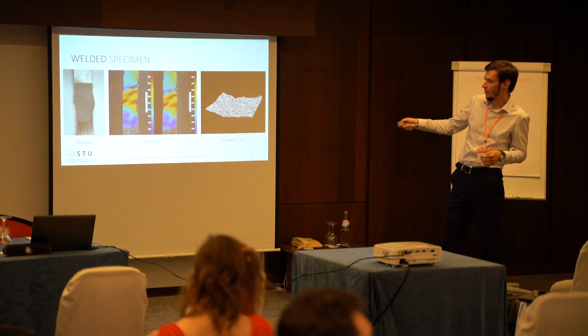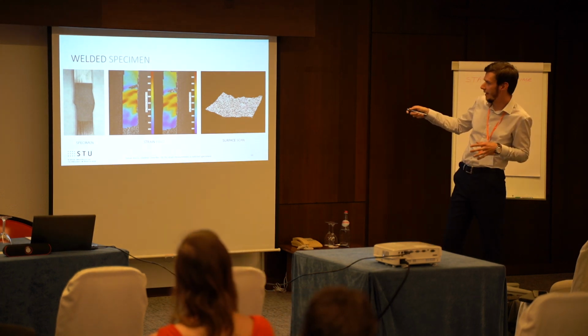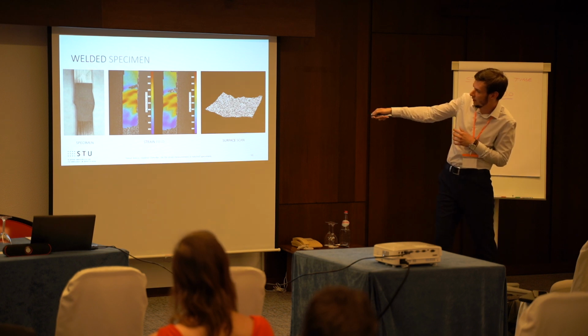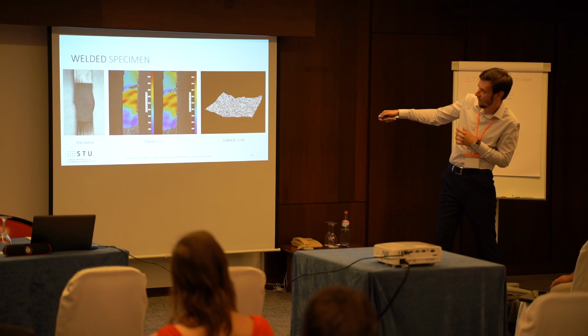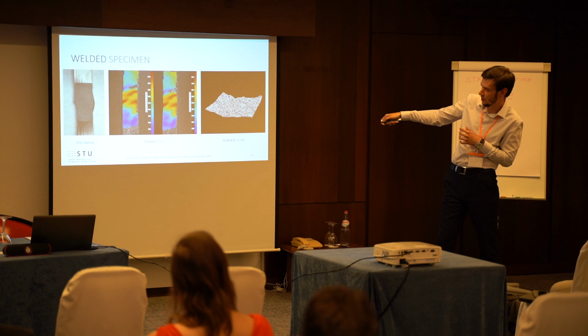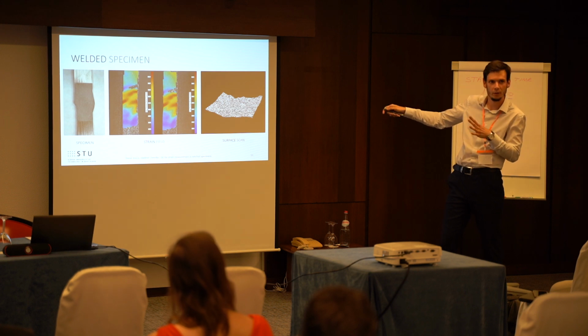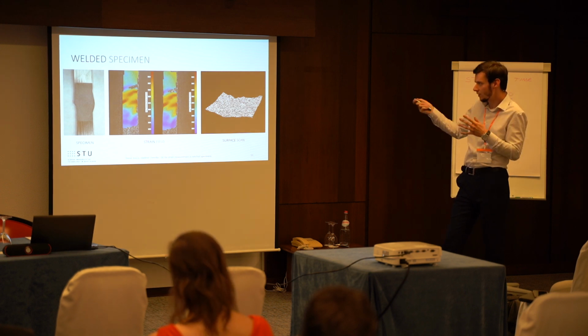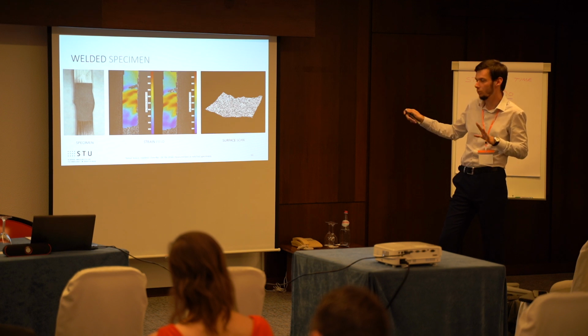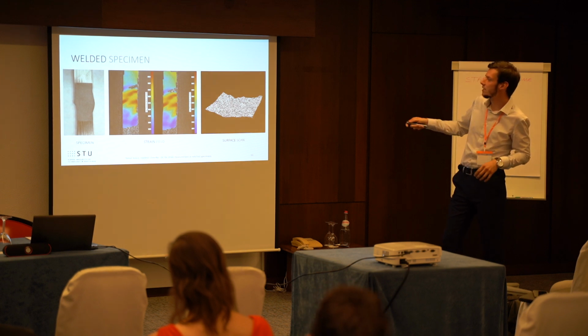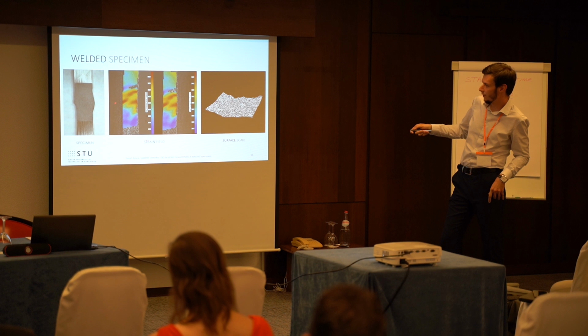Here you can see the measurement from the first measurement case. Here you can see a little bit of an undercut, and these higher values are the undercut, and here comes the weld, and these are the smaller values right here, and this is the base material, or the heat affected zone, in better words. So here we have 2 significantly critical points.